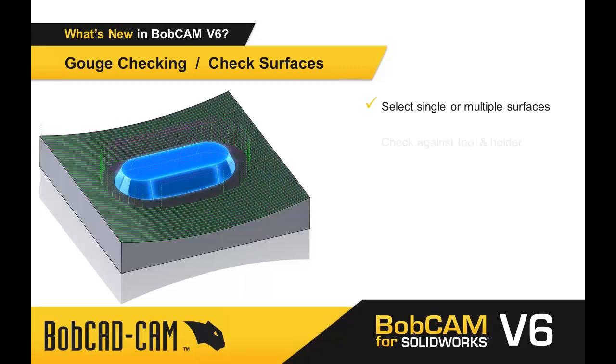You can also check against either the tool, or the tool and the holder. So when you've selected some surfaces that you want to check against, you can check your tool or your tool and holder, and there are a lot of clearance options for that as well. The other thing you can do is retract or bump up your toolpath. If the tool makes contact with one of these surfaces or all of these surfaces, you can tell it to bump up by a specific amount.